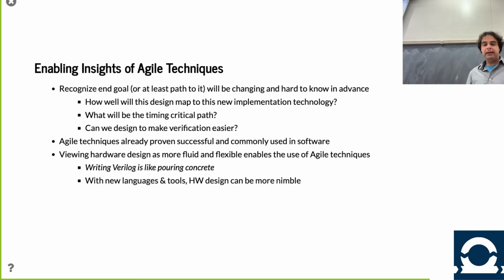And what's interesting is, if you look at what will enable this, well, the language that's commonly used, Verilog, I actually argue is like pouring concrete. That language builds very functional and correct hardware, but it's actually hard for humans to get it right. That language, despite the specifications being over 1,000 pages, has plenty of behaviors that are undefined. And so as a result, in order to make this code robust, people who write Verilog are constantly using things called linting tools that check their code for things that aren't against the rules of the language, but lead to safer behaviors. So it's this very careful, deliberate process of writing the Verilog. Once it's correct, you don't want to mess with it.